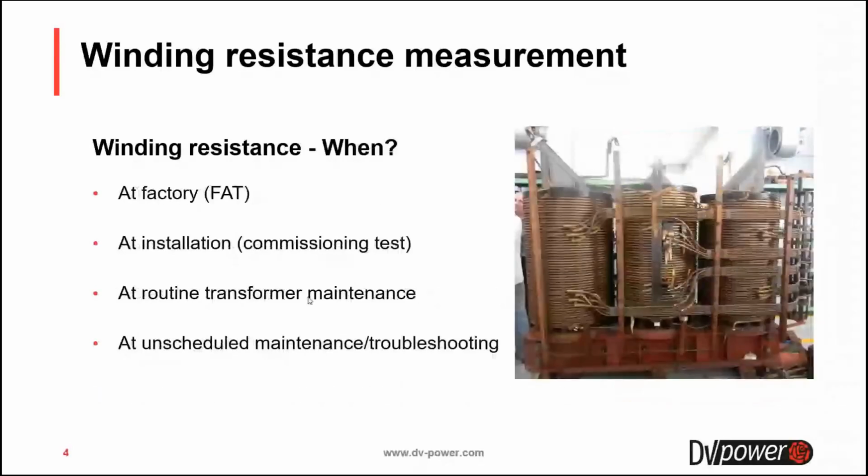The first winding resistance test we can do at the factory during the manufacturing process and during factory acceptance testing at installation. The risk of damage is significant every time the transformers move. Because of that, every time we move a transformer, we must do winding resistance.